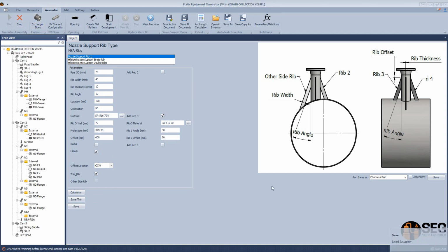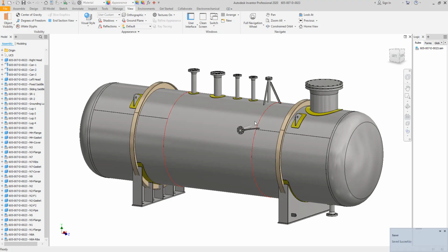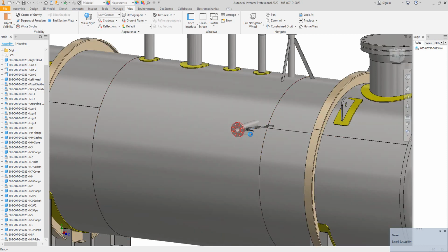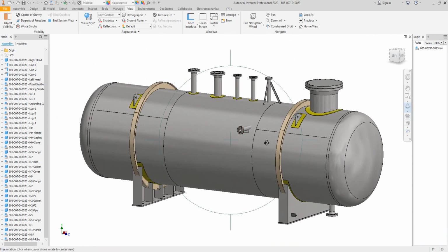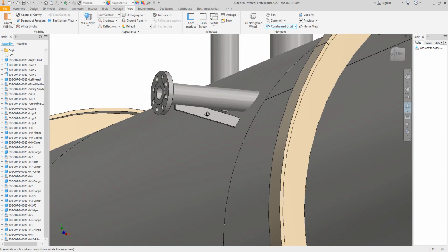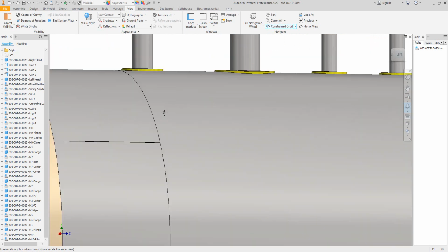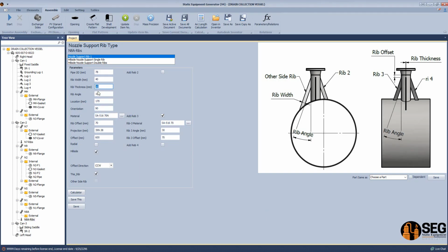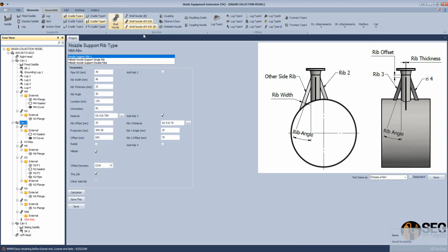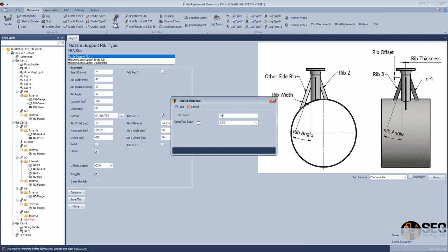Now let's click run the assembly. Here the first rib appears, so the sketch needs some modification. So now I think we can change the value. It's with 10 degree, so we can change that value now to 30 degrees. Okay, and let's add another nozzle, which is N8B.